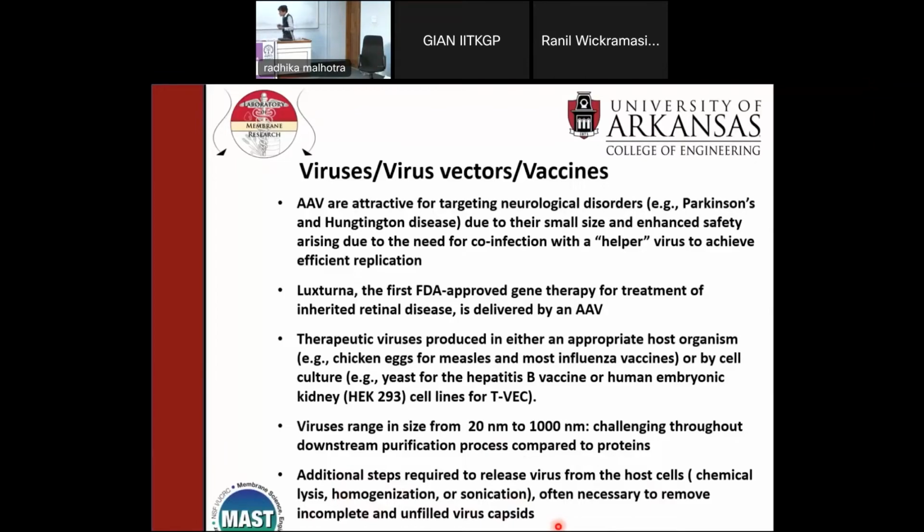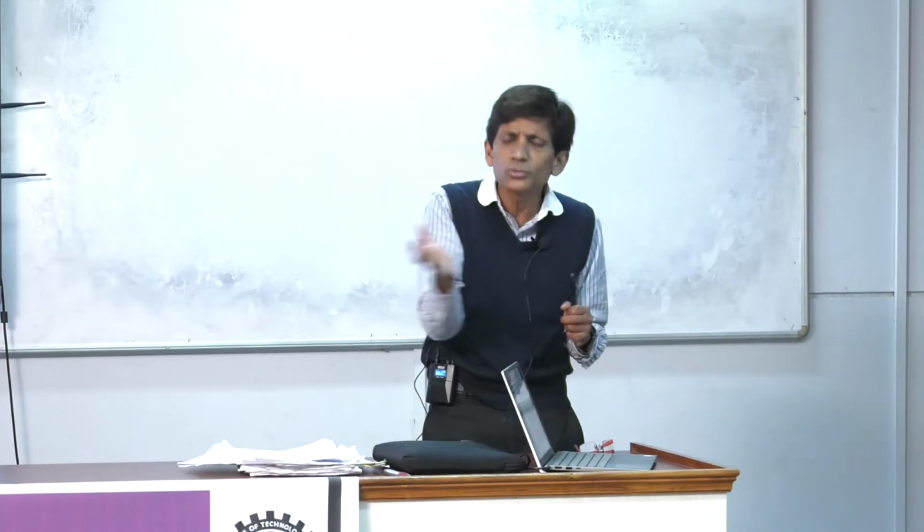If you remember, we talked about bioreactor harvesting, and we said that in most cases, for therapeutic proteins, except perhaps in bacterial cells, they are excreted in the growth medium. That helps a lot, right? Then you have the protein of interest in the growth medium, the cells excrete the protein, and then your first purification step, the harvesting step, is removing particulate matter.